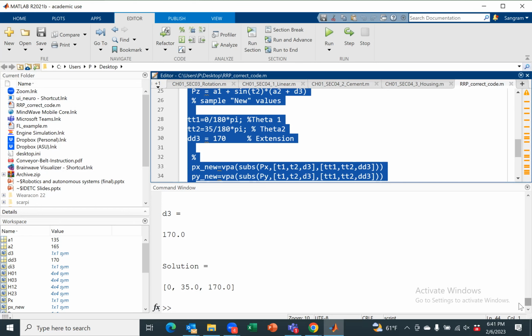If you get a robot arm that has 4 or 5 or 6 joints, first you have to separate the first 3 joints. You can only do inverse kinematics for 3 joints at a time. Why? Because you have px, py, pz, only 3 equations.